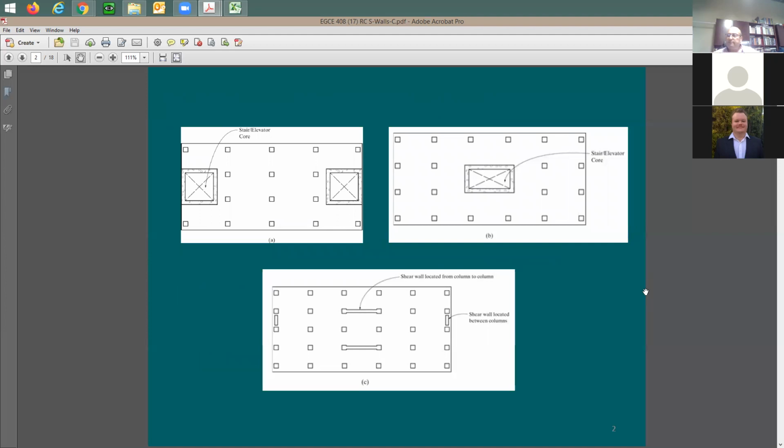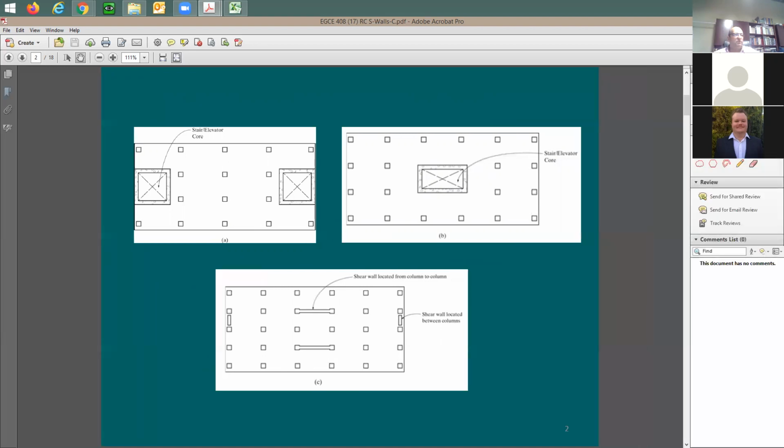So what is a shear wall? A shear wall is that concrete wall that you put in a building to resist seismic forces and wind forces. Seismic forces and wind forces mean forces due to earthquake or forces due to wind pressure. And this force is going to be a horizontal force, meaning I'm expecting the horizontal force to come this way, right? Or it's going to be coming this way. Because you cannot control what direction the earthquake is going to be pushing your building. So it can happen in both directions, longitudinal direction, transverse, or X and Y direction if you like.